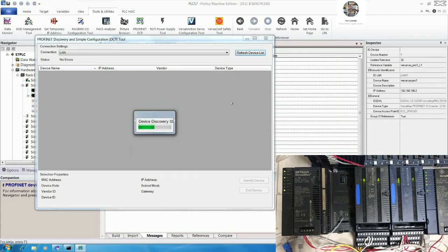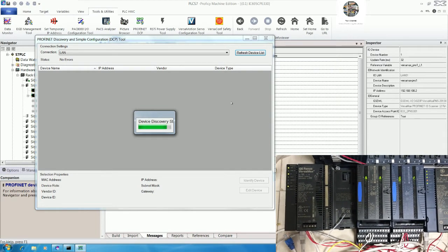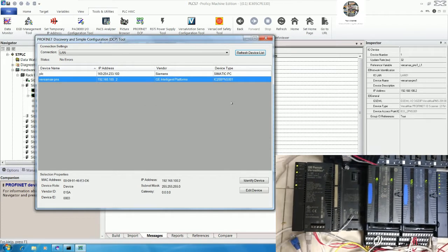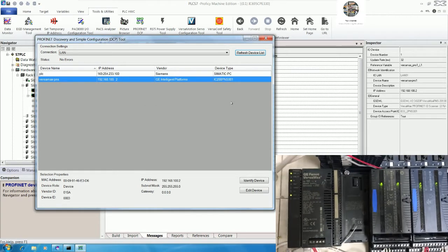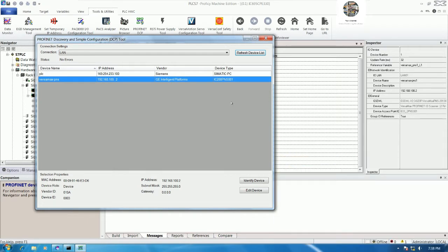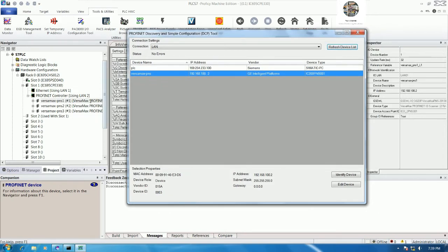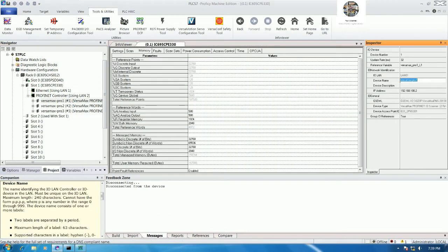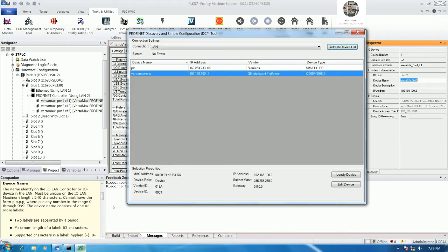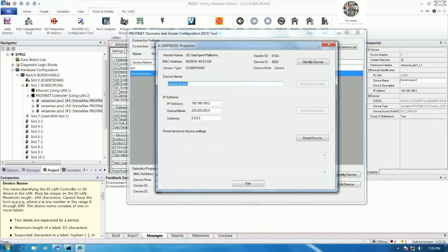When scanning, let's see the blinking LED. So right now we detect, yes, it detects one for this PNS. So let's check, the name should be like this. So I will copy, yeah, Control C, and then double click here, then change the name to this one, and the IP address is correct, so we don't change it. So set only the name, okay, and then click exit.